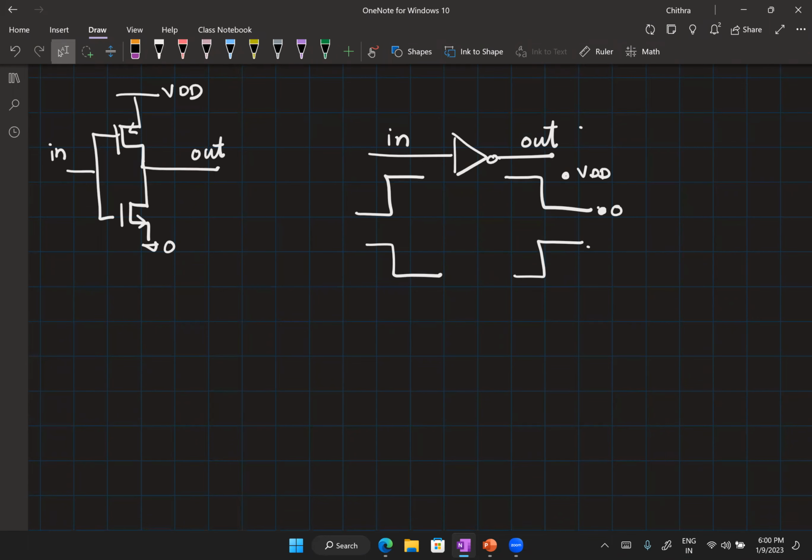As you might have guessed, this is basically an analog course. Now, anytime we deal with an analog circuit, our general mode of analysis is to find a bias point and then see how we can apply small signal analysis around that bias point, right? So the question is this: can we use the same method of small signal analysis on the inverter when it is driving a clock signal?